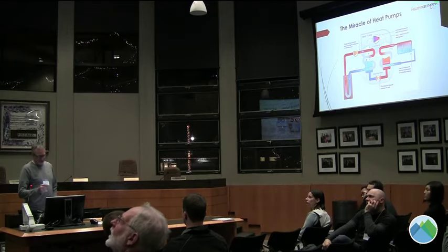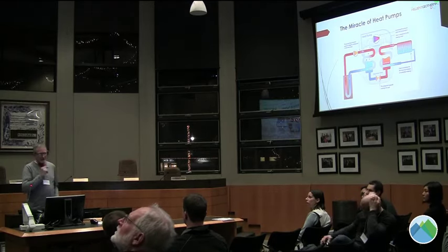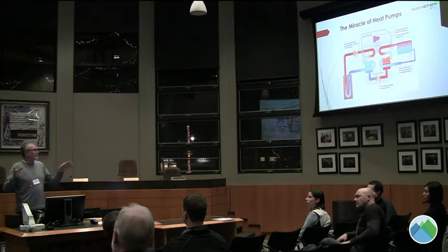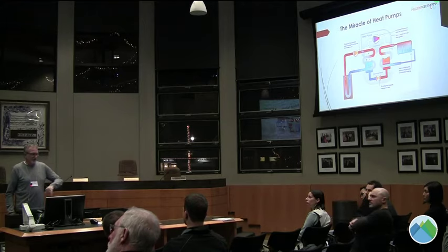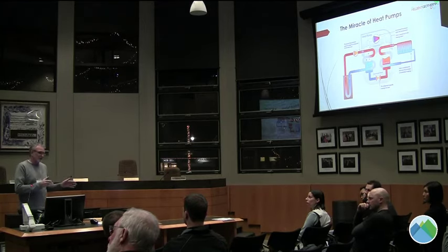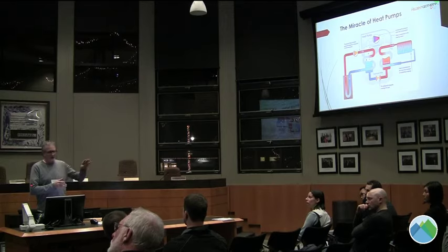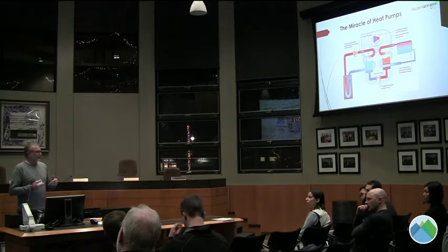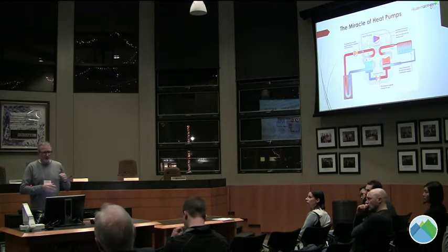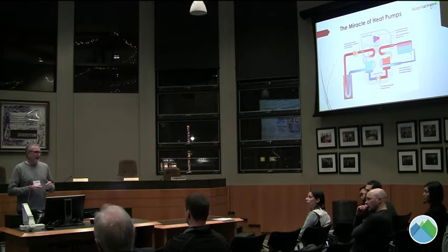So basically, you have refrigerant circulating through the center of the heat pump. You have a compressor with two heat exchangers, one on each side. Refrigerant is circulated through these, and on the source side, say we've got groundwater coming in. Now, refrigerant is pretty cool stuff, so it will vaporize at very low temperatures.